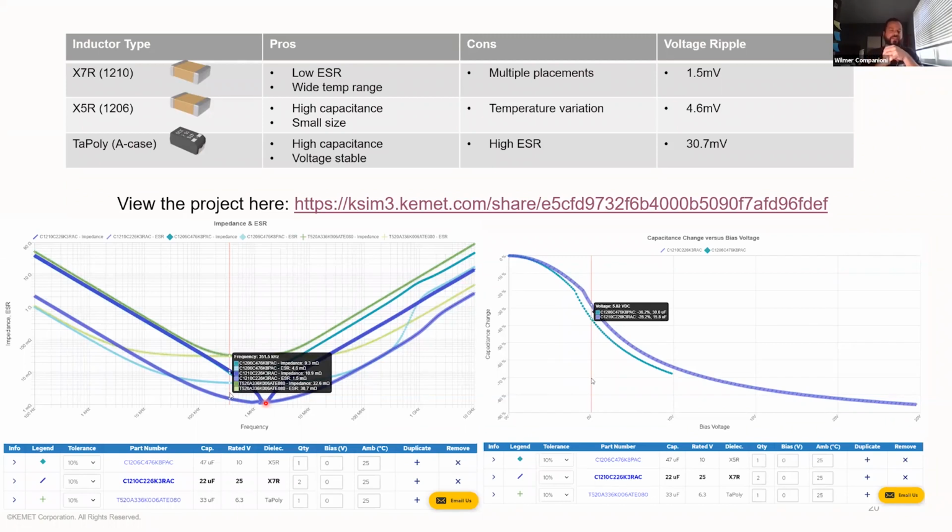So we have, let's call it, some characteristic equations that give the shape to these plots and curves as they appear on the screen. And those equations have coefficients and related constants that ultimately change the shape of these curves. So we take measured data and we change those coefficients until the simulated curve, the modeled curve, lines up right on top of the measured data, and then we save it that way.